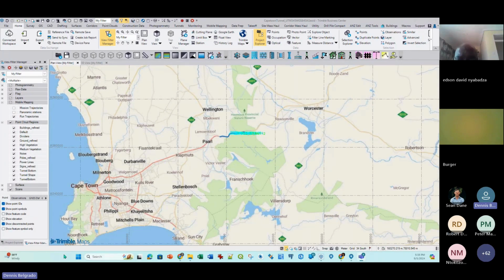That can give you really, really accurate data. And in this data, of course, I'm taking this one as the worst scenario, because we're using GNSS, GPS, GLONASS, and all that stuff. Of course, we have to have a view to the sky, right? But when you go into, let's say in this case, a tunnel, all of a sudden we don't have a view to the sky and we don't have satellites, right?